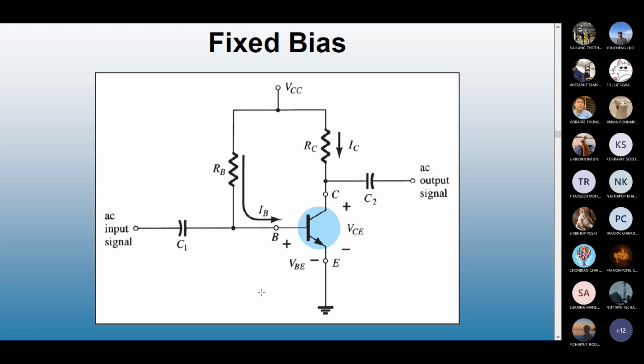And then we have to connect the signal, right? The input signal is an AC signal. It is connected through a capacitor to the input base side. If you want to take the output signal, you take the output from the collector. This is a common emitter fixed bias. You take the output from the collector, through a capacitor, and then measure the output signal.